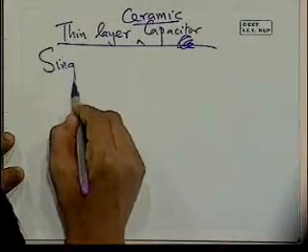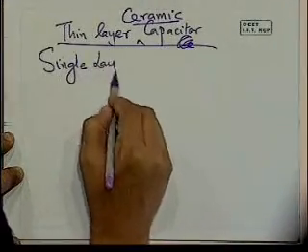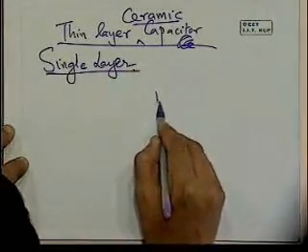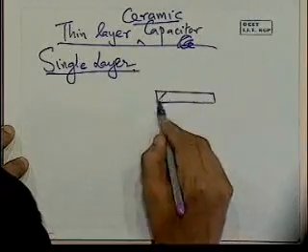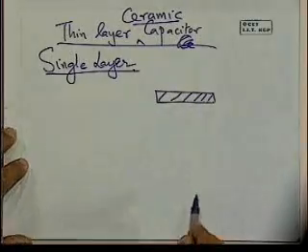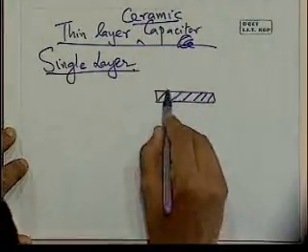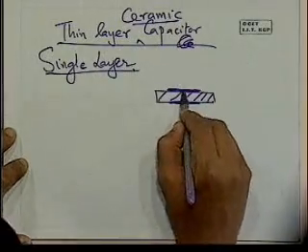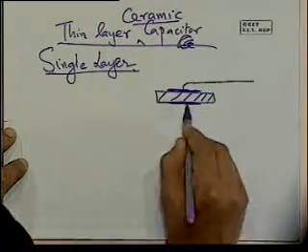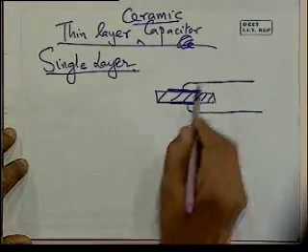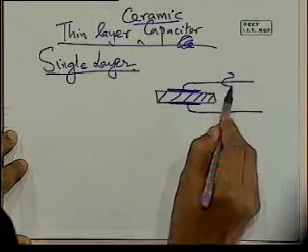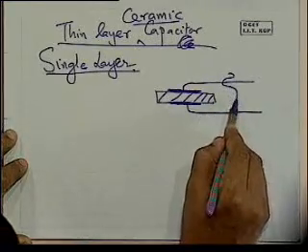We'll look at the single layer model. And the essential construction is very simple. We have the ceramic. On both sides of it, there are contacts which allow us to connect the leads to it. And the whole thing is encased in some epoxy package.